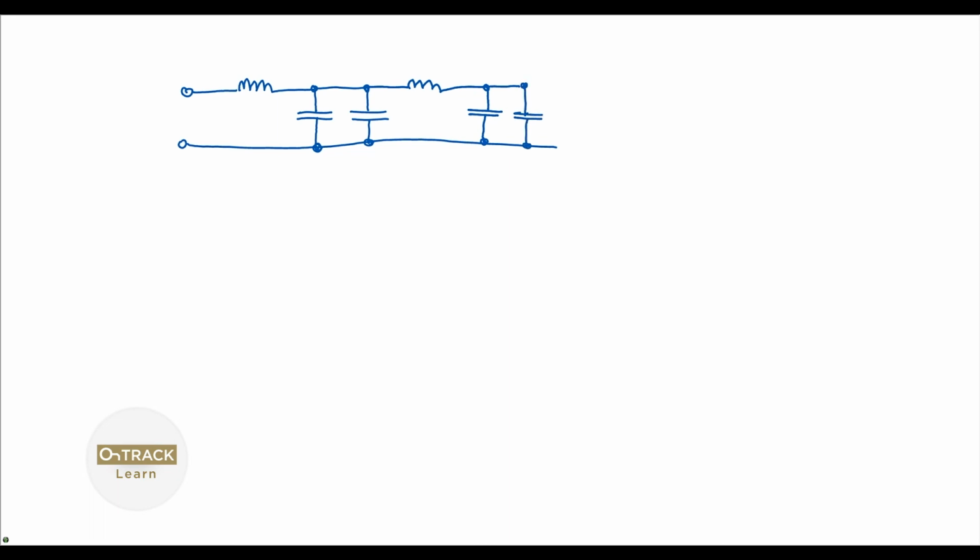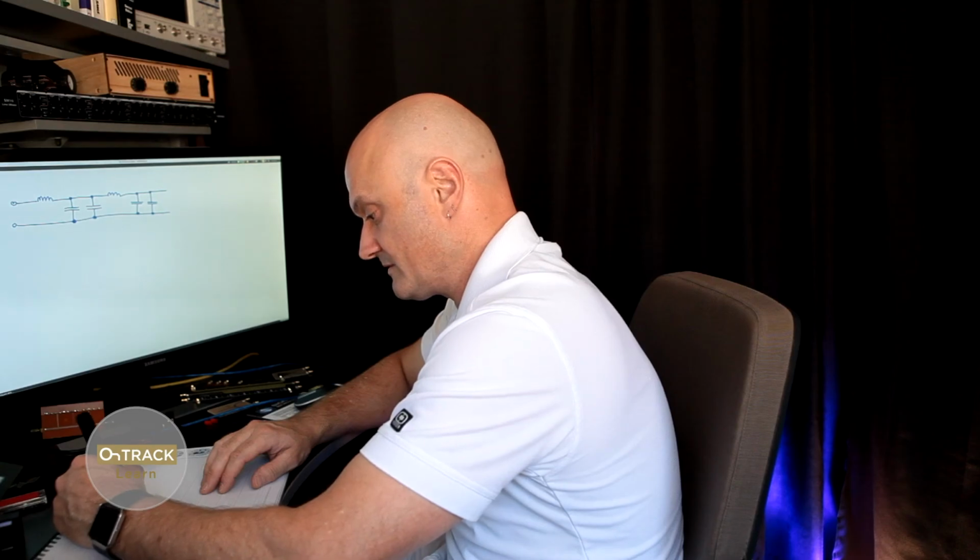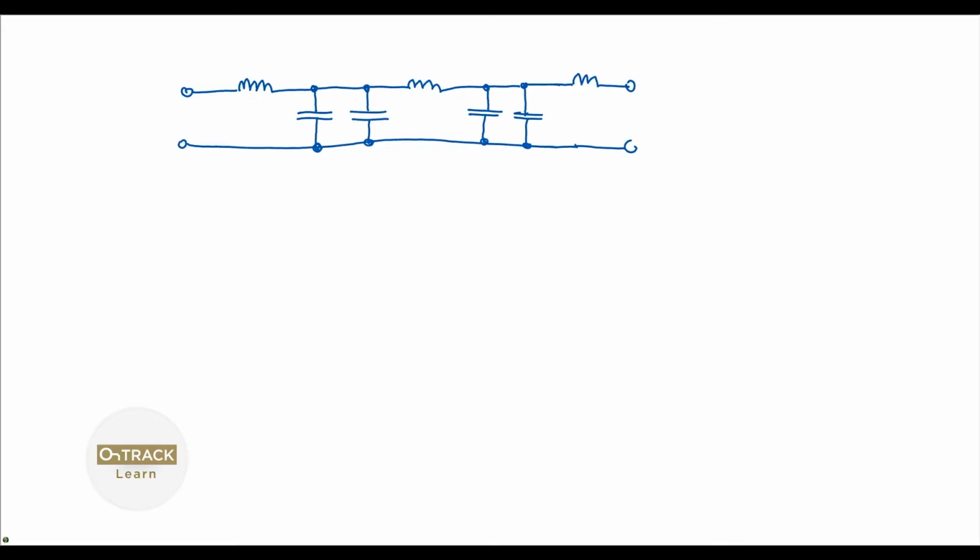So if we have our input, we want series inductance, we're going to have big capacitance to ground, and we're going to have more than one of those because, to reduce the space required, we put a couple of radial stubs and then a couple more separated by more inductance. Right? And then of course we have some transmission line segments on either side of that, on the input and the output of the filter. And so this is a pretty good low pass filter.